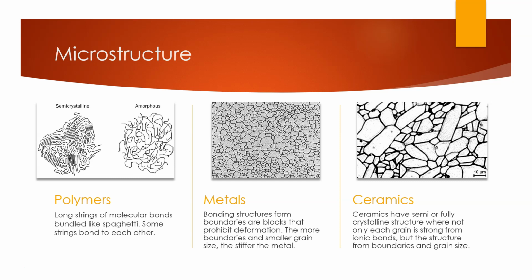Metals have a very defined grain structure. The one shown in the image is carbon steel that has been tempered with heat. Within each bond cluster, the atoms can stretch and deform, but at the boundaries, you would have to break a bond in order to move that boundary. This means that the more boundaries there are, the more brittle the metal. The fewer boundaries, the more ductile. This can be manipulated by heating metals up, adding to the atomic energy, and then quickly quenching it to the configuration you desire. This is referred to as heat treatment.